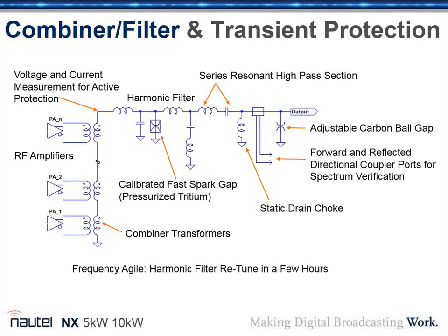Right. So the tritium is essentially, in that spark gap, there are some free electrons floating around. That means the spark gap will fire a lot faster than just any air spark gap. And the point of having it at that point is that when it fires, it presents a short circuit across that capacitor bank and essentially presents an inductive load to the power amplifiers, which they're happy to switch into. Okay.